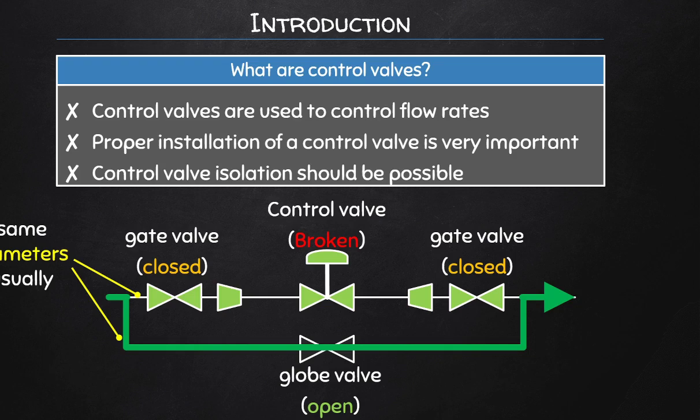And eventually there was a pressure drop, fumes started to go backwards through the process, and eventually ended up in an electrostatic precipitator in the presence of air, and with the electrostatic discharge, it blew up the plant. It was really bad. So it's very important to design valves correctly and also operate them correctly. So that is what we are going to go on about currently.